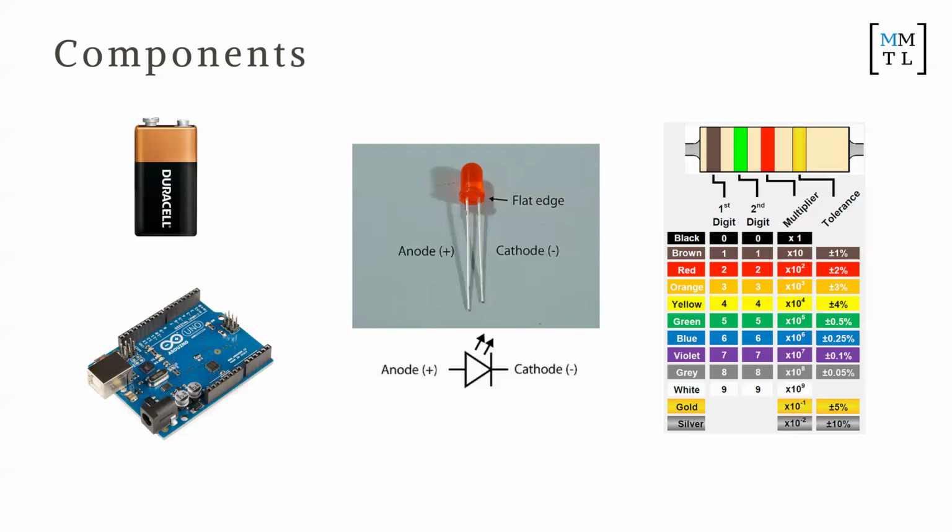Does that make sense? So please make sure that you get this polarity right. This is the anode and this is the cathode. When you look at the diagram later, just make sure you know which side is which, because if you put it in wrong, it's not going to work. So see if you can find the polarity of the anode and the cathode.